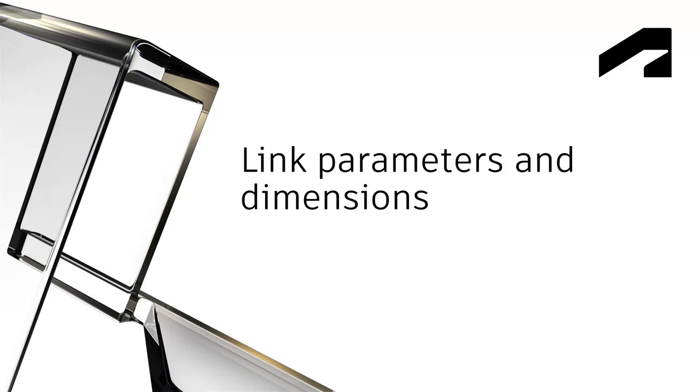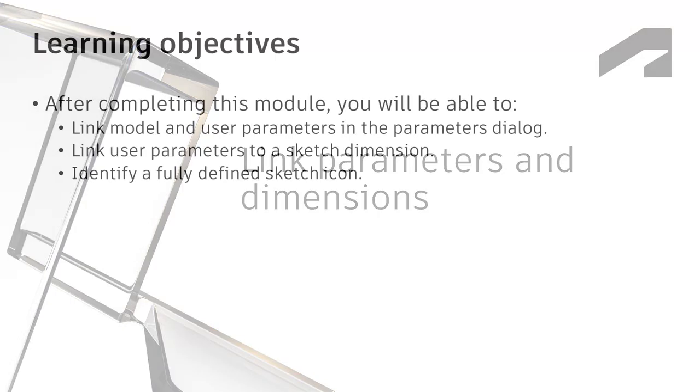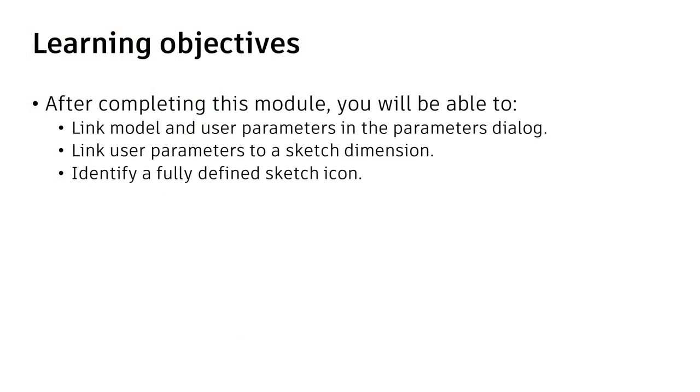Link parameters and dimensions. In this video, we'll link model and user parameters in the parameters dialog. We'll link user parameters to a sketch dimension, and we'll identify a fully defined sketch icon.